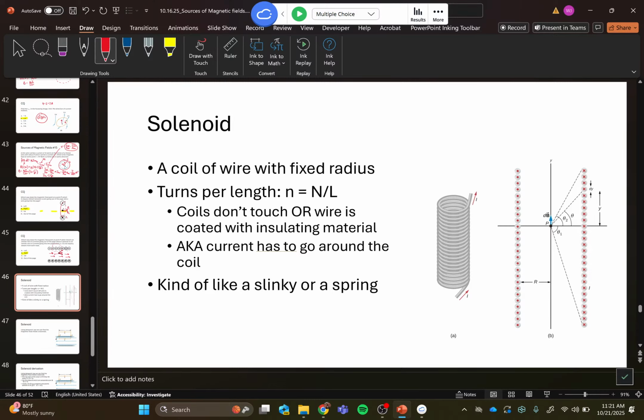This is an engineering thing. Your wires need to be covered. Obviously if it's covered with rubber, that's insulated, like you all see wires covered with rubber. Just a fun fact for you all, there are wires that are insulated on the outside, but it doesn't look like it. There are these copper wires that have an orange tinge on the outside. I don't think it's bare copper. It's not. It's a very thin painted layer of insulation on it. So you can make these wires really thin, not by coating them with rubber, but by coating them with this paint. We're going to call it paint. This insulating thin layer. You don't need that much insulation. And you might not be able to tell that, and when you plug stuff in, you're like, why aren't I getting any connection? You actually have to scrape that off if you want to connect it to something. So that's just a fun fact for you.